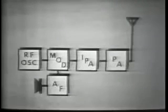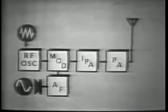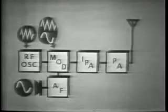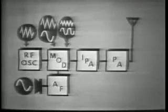Now, you know that in an AM transmission, an RF carrier is required, and that for 100% modulation, an audio frequency of equal peak amplitude is needed. When the two frequencies mix, the result is four frequencies: the two originals, the sum, and the difference frequencies, which are called the upper and lower sidebands.